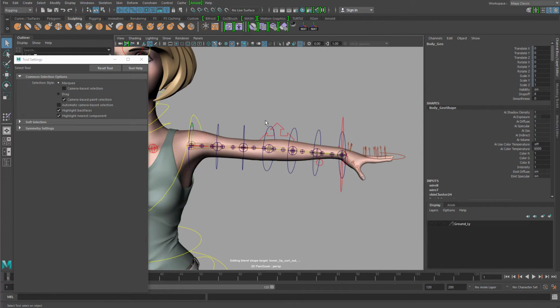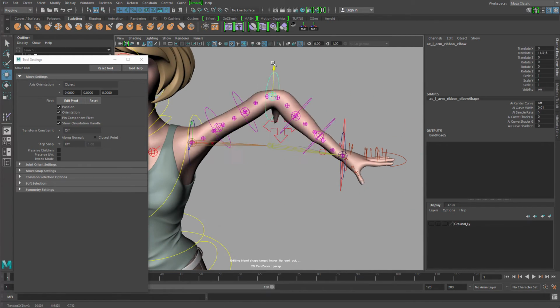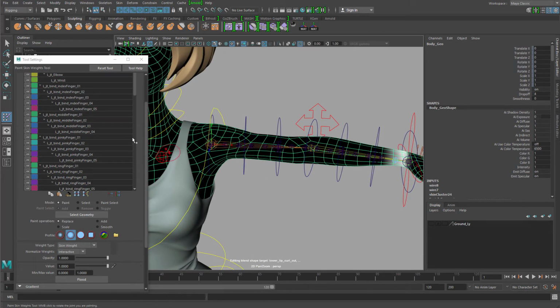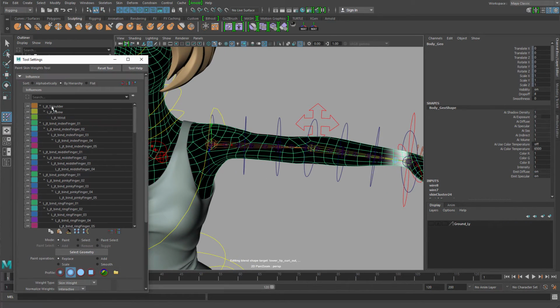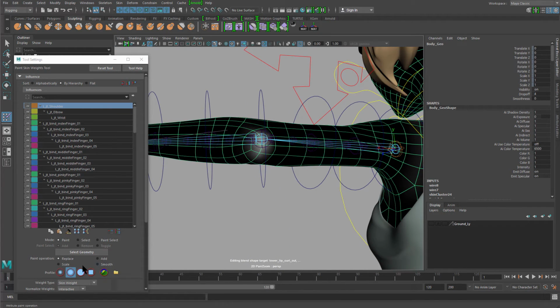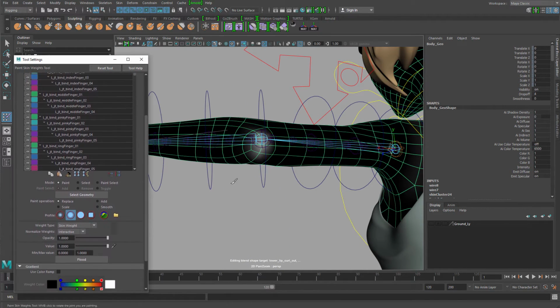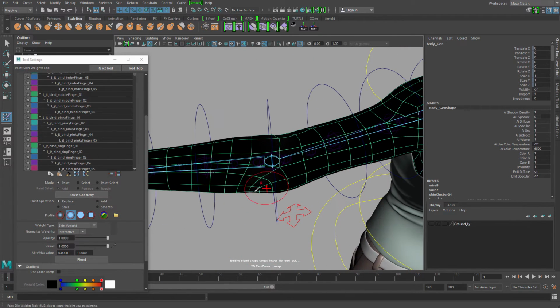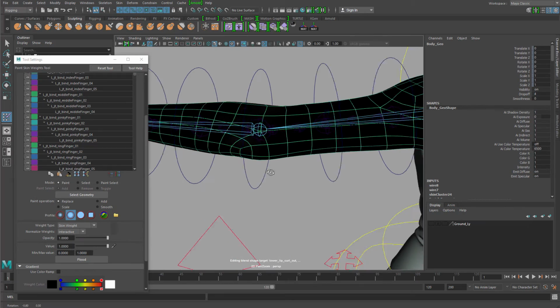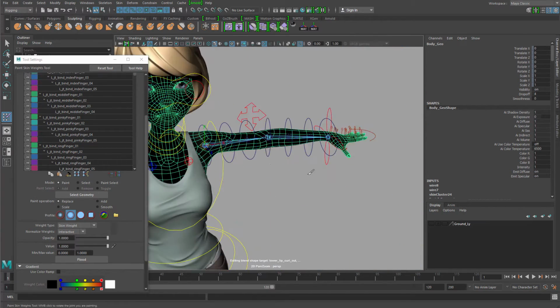And of course, you can only see if it's working by trying to drag the controller. Okay. Of course, there is something wrong down there. One of the things you can try is go to the list and find the shoulder joint, making sure it's not having all the weighting here. You can use subtraction now. The reason you can use subtraction is because when you subtract those things, they're going to be proportionally distributed to the joints around it, because they are the only joints that have weighting over there.